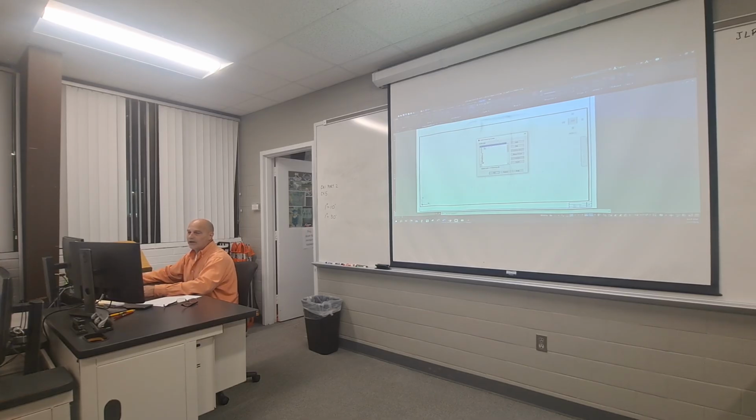So I can go through there, I can take some of these and I can say, well, I don't want this here, let me move this down some. I use this one a lot. Let me move that one up. Put it up here at the top of my list. Remember, I'm only changing it inside this one drawing. The only one that you cannot delete off this menu is 1-to-1. You cannot delete that off of there. Everything else, your architectural scales, all of this stuff can be deleted from this menu.